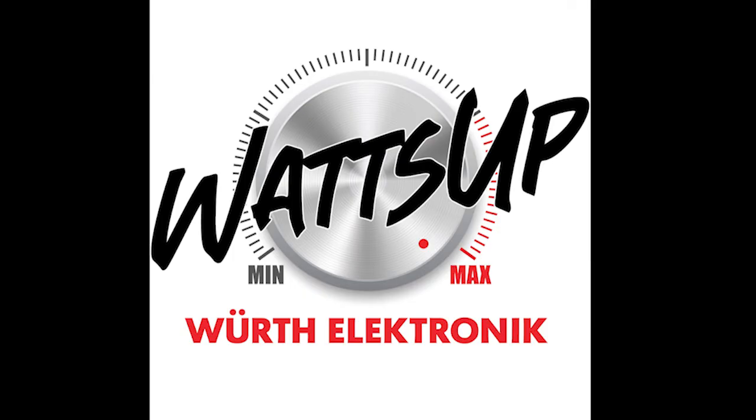Now, when we talk about the bend radius or the flexibility of a cable, this represents the sharpest bend the cable can withstand without potential damage and degradation of performance. Overbending the cable damages its internal structure, and it will directly result in poor electrical performance of an assembly. Cable bending radius does not have a direct result to cable thickness.